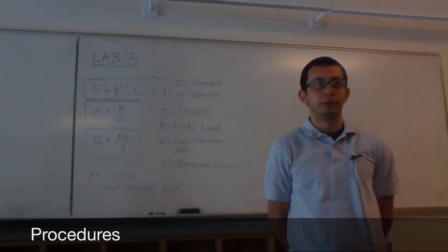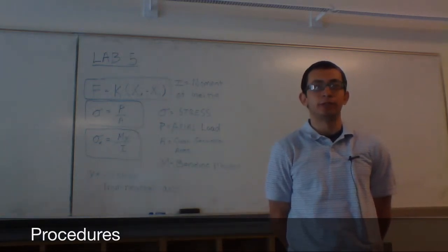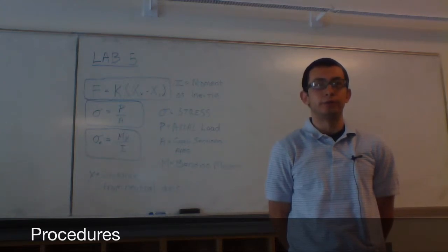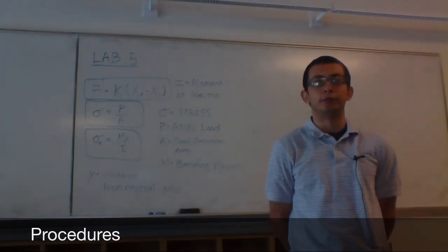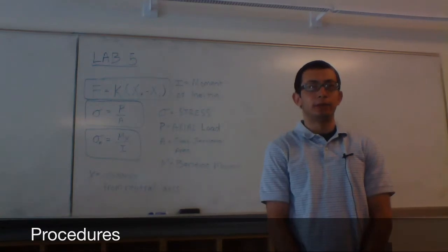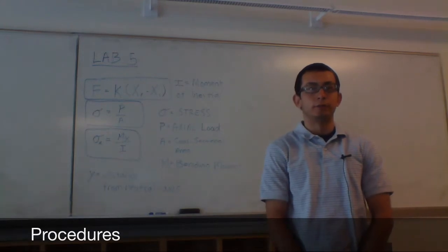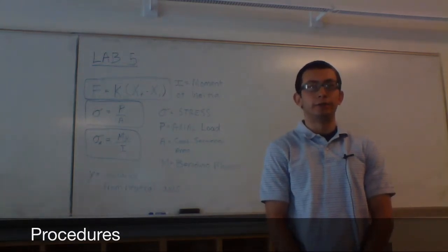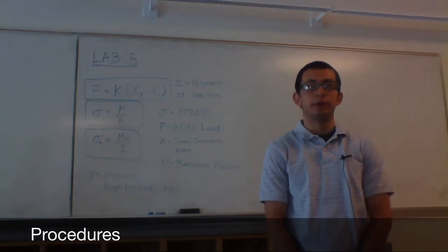For the procedure, the teaching assistant will perform a simple tension test on the Instron Universal Tester using the 1018 sheet metal specimen. 2 strain gauges are mounted parallel to the direction of pull and should report the same values. Their results will be averaged for greater accuracy. Instead of allowing the Instron machine to continuously record force and extension values, the testing will be paused multiple times as the load increases to record the load and strain values from the gauges on the attached data sheet. That data will be used for further analysis in the lab report.